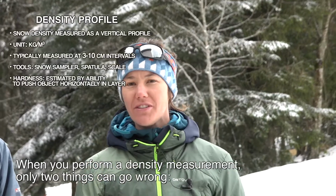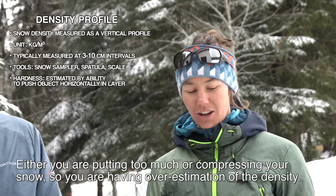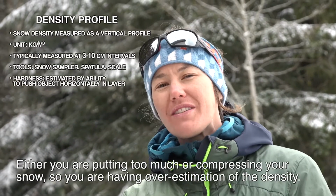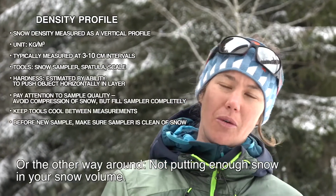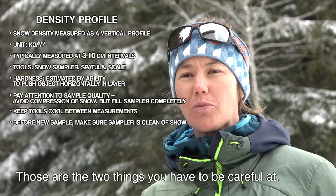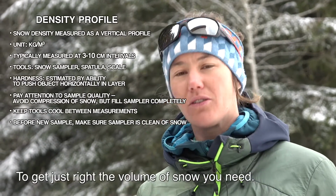When you perform density measurement, there are only two things that can go wrong. It's either that in your given volume you are putting too much, you are compressing your snow, so you are overestimating the density, or it's the other way around, putting not enough snow into your volume. So those are the two things you have to be careful about. Get just right the volume you need.